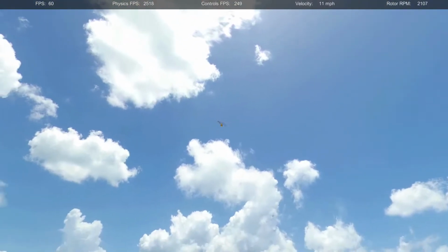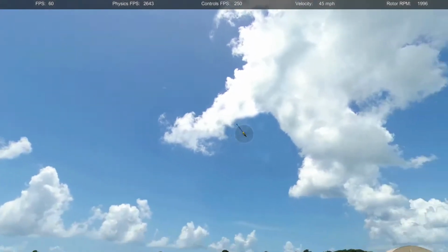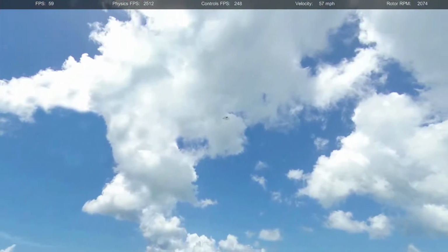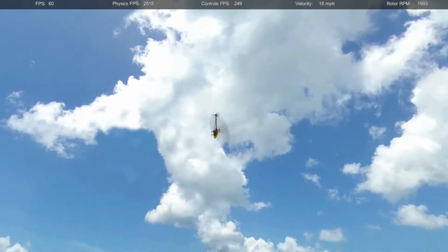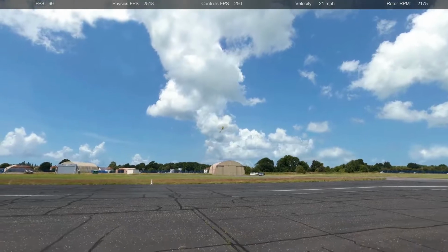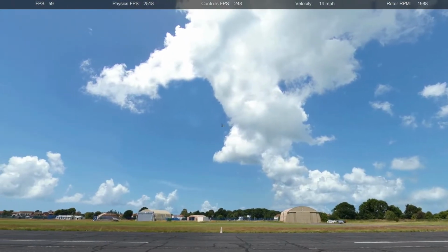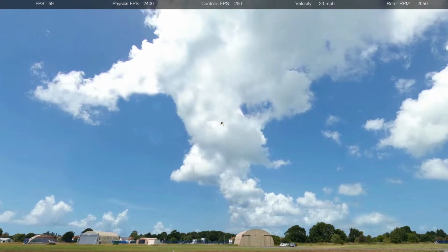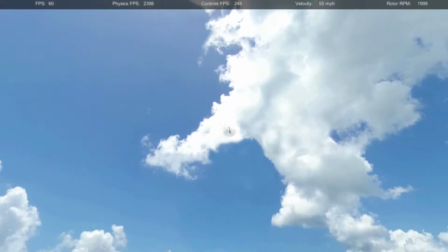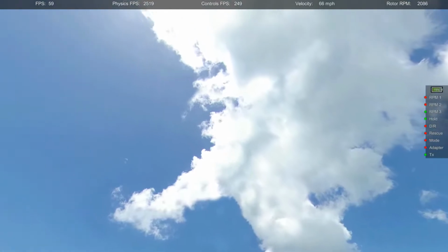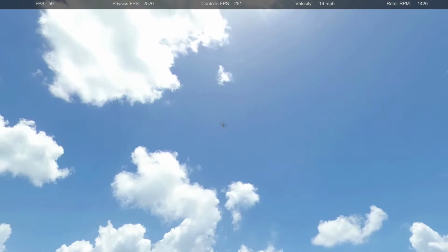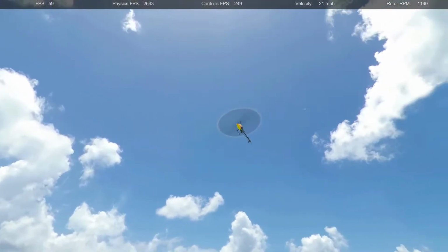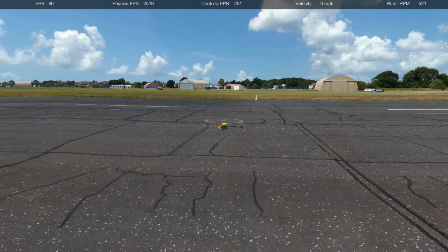And when they patent the airplane in 1906, this is the drawing in the lower right of their patent. And you notice there are no propellers, there are no engines. What they patented was the control of the airplane, not on the fact that it was powered. This was that important. And so everyone since then has needed some direct method of yaw control. A rudder is the easy way to do it, but you could also create drag at the wingtips in order to be able to fly aircraft.